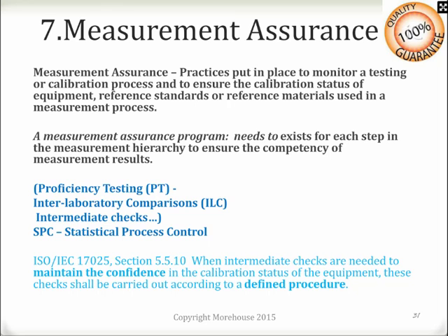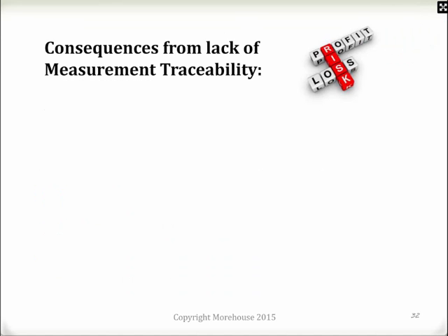So per section 5.5.10 of ISO/IEC 17025, when intermediate checks are needed to maintain the confidence in the calibration status of the equipment, these checks shall be carried out according to a defined procedure.